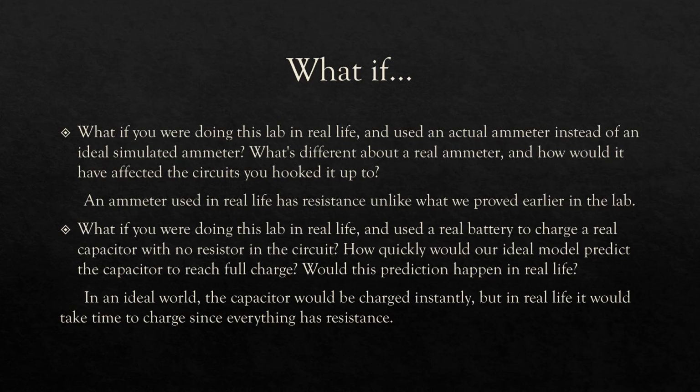What if you're doing this lab in real life and use an actual ammeter instead of an ideal simulated ammeter? What's the difference about a real ammeter, and how would it have affected the circuits you hooked it up to? An ammeter used in real life has resistance, unlike what we proved earlier in the lab.